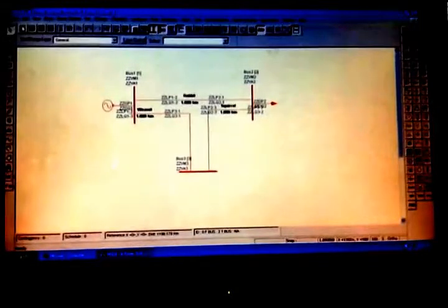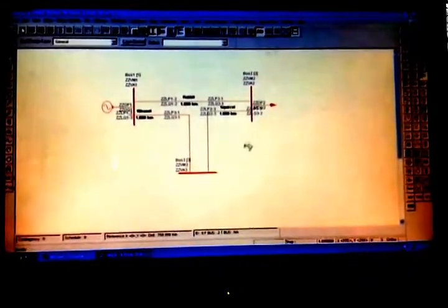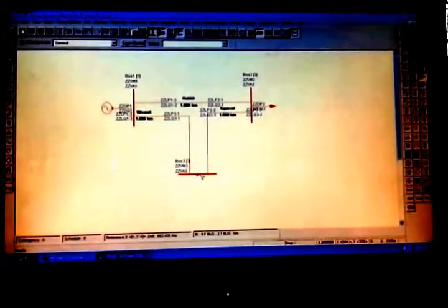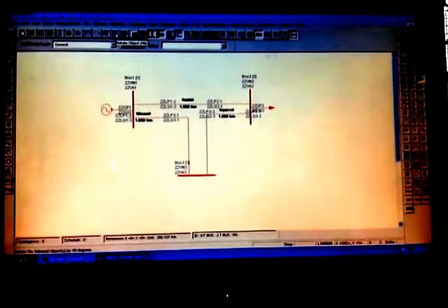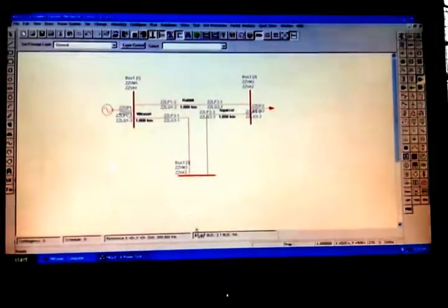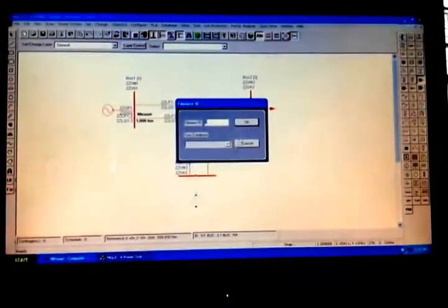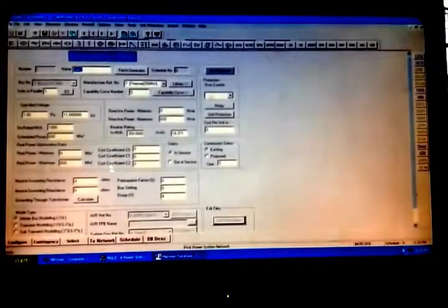So first deselect this. Again select one more generator and again you have to place it correctly on bus 3. So you need to rotate 270 degrees. Now place this. Okay. Now again here we need to select the library which is equal to 200 megawatts. So I chose 210. Now the MVA rating for this is 250. 200 megawatt. Now save this.